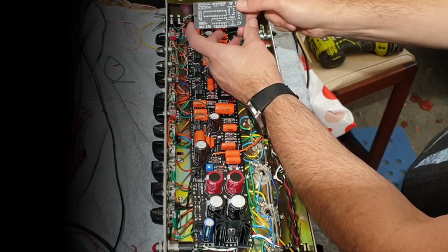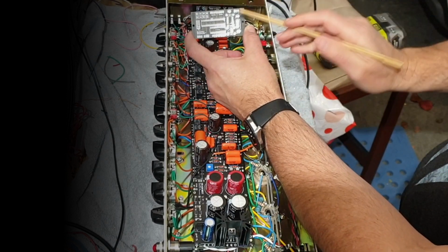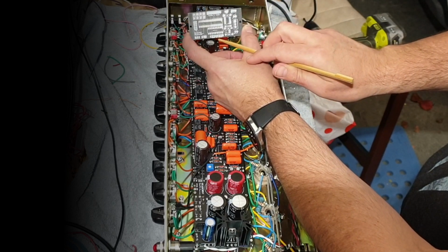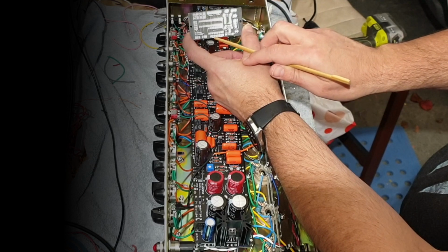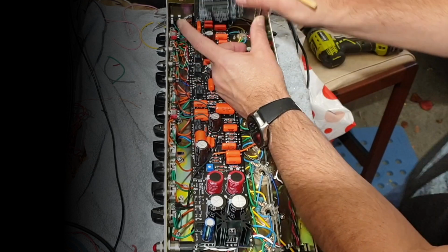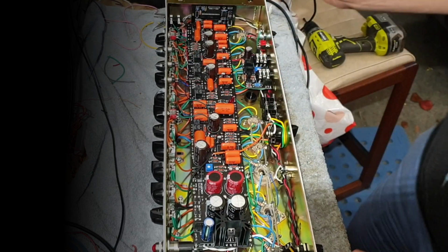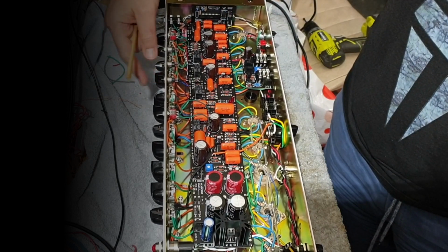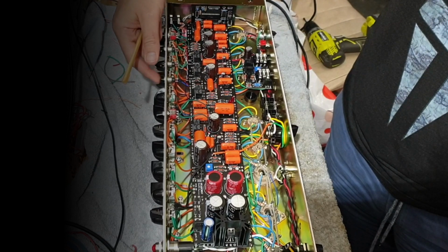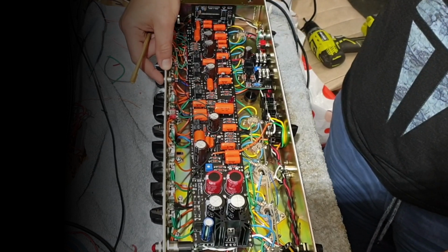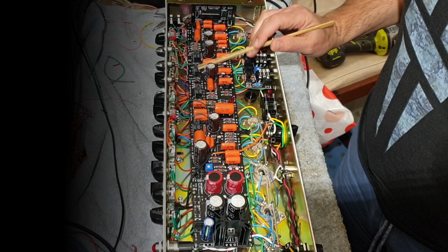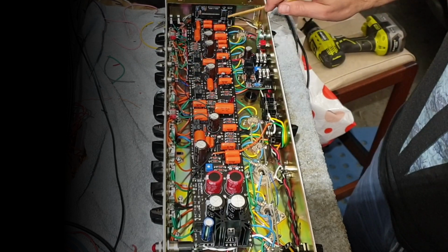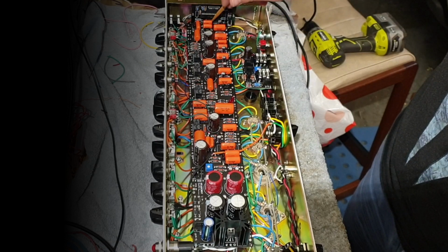Here we go. Here's our board. Hopefully that's coming through. So I've got 1, 2, 3 on the input toggles, and down here is where you connect your relays. So toggles 1, 2, 3. You need to make sure that you match them up. If this is 1, this is your lead boost function, which is this relay here. It's R3, right? So R3 needs to connect to toggle 1 on the output.